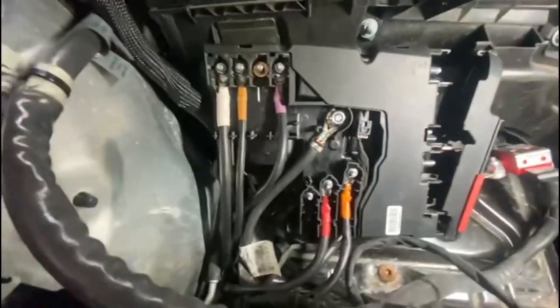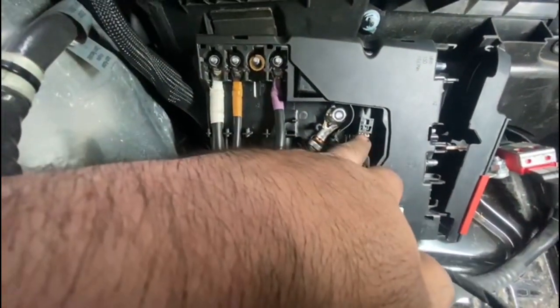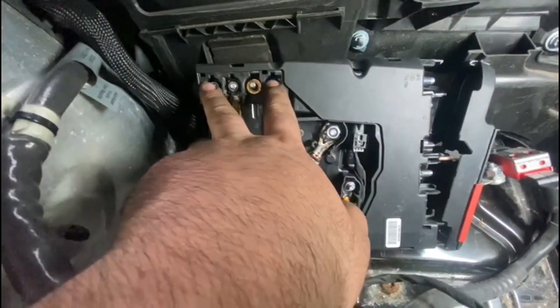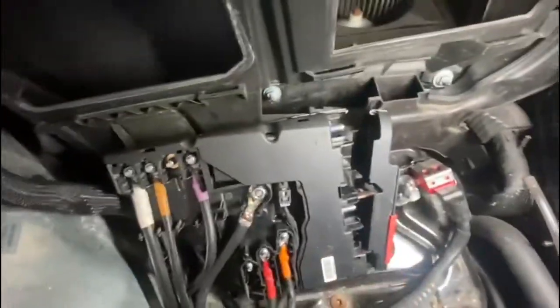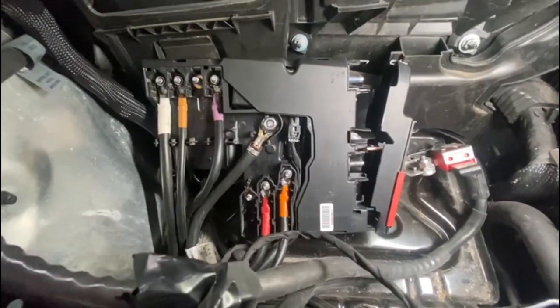When you take this off, make sure you take a picture of which wire goes where. And this plug as well. It's got a cover here. You've got to remove the cover to get access to these. When trying to remove the SAM module, you'll have to remove the battery, because the SAM module sits right here and you're not getting any access to those bolts without removing the battery, moving the SAM module here, taking off the cover and taking off as so. Make sure you take off the auxiliary battery as well, just in case.